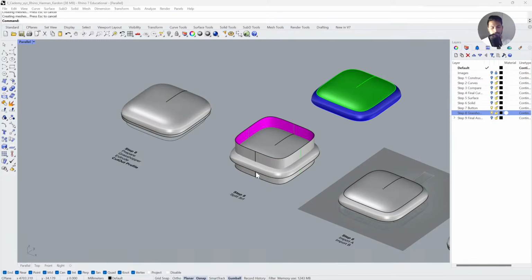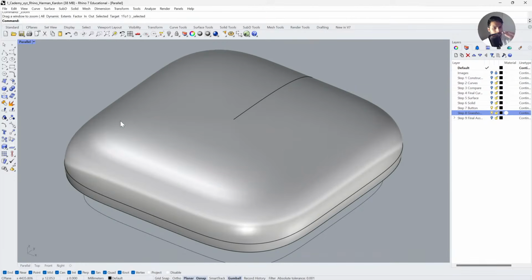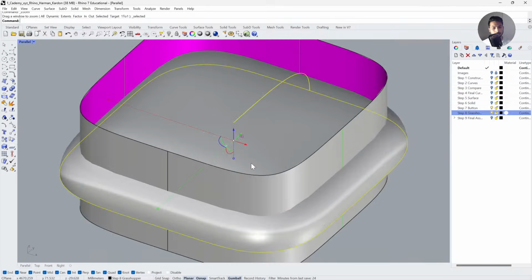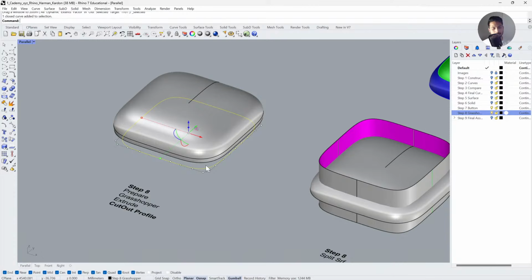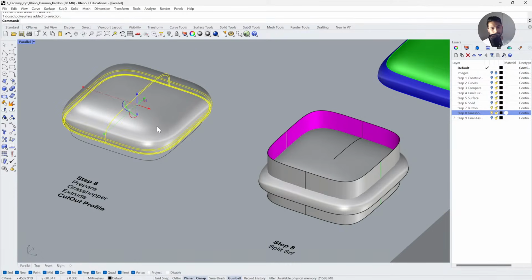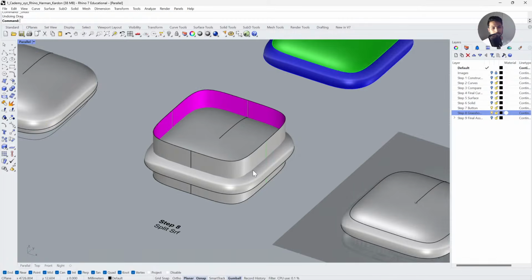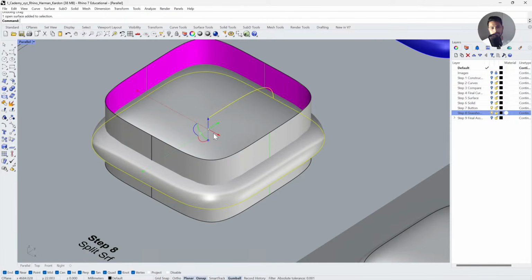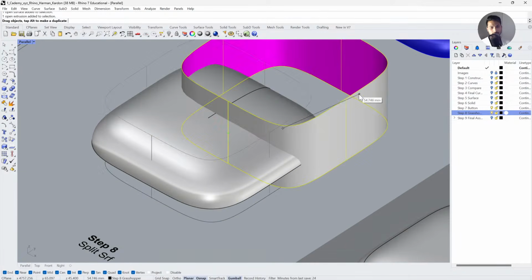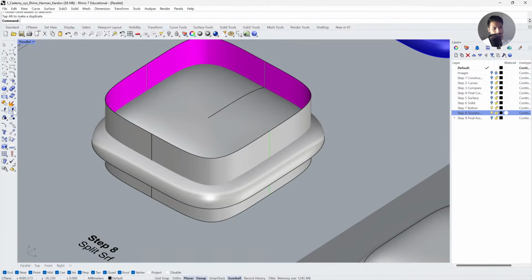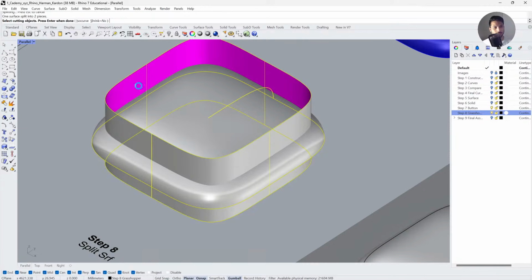All right. So for the Grasshopper part, we just need the top surface. Okay. So here, what I will do is I will use the curve that we have generated, and I will get rid of everything except the top face, and then we will split the surface with this curve. Okay, so I have extruded the curve. Let's split this with that.